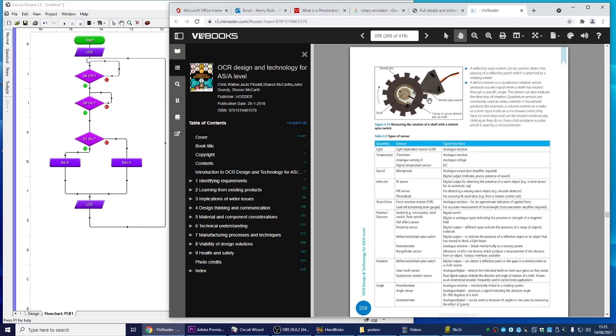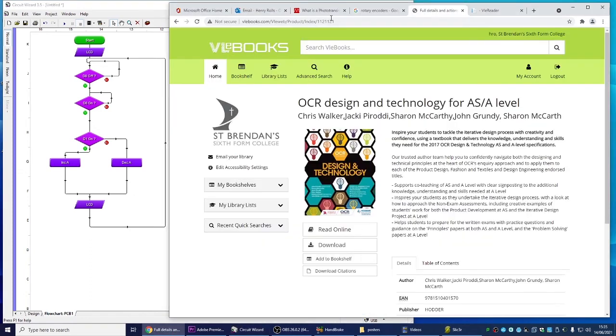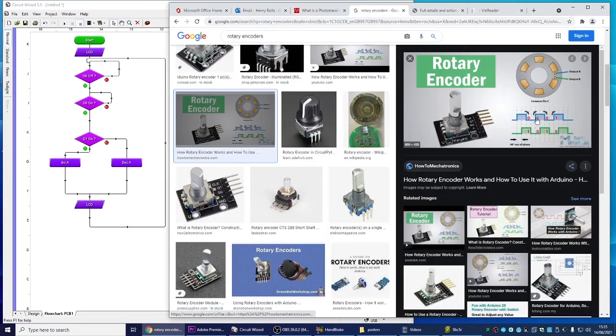So in other words, just 90 degrees shifted. So half of that slot is on when the other one's fully off. You see what I mean? We'll use the same principle. But yeah, this flowchart here, it's basically the principle of how to tell what direction it is when you've got two things that are slightly out of phase from each other like that.